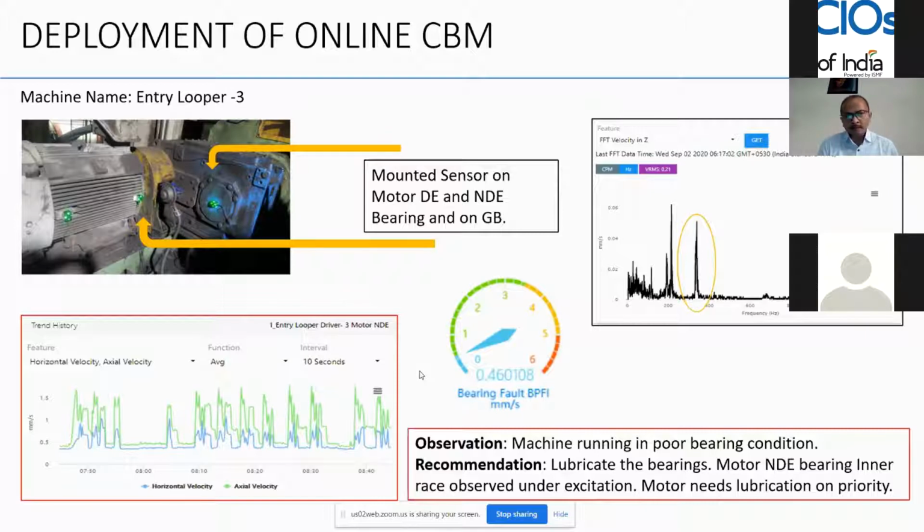So what I'm saying is that in some critical applications where you use shaft displacement, up to the bearing for the vibration monitoring, which is typically done for general hydrodynamic bearings, I think again there is a bandwidth issue. It becomes a little more invasive. But I think most, just hold on, Ronak, hold on. Non-general bearing. Ronak, hold on. So I think there is some bandwidth issue.